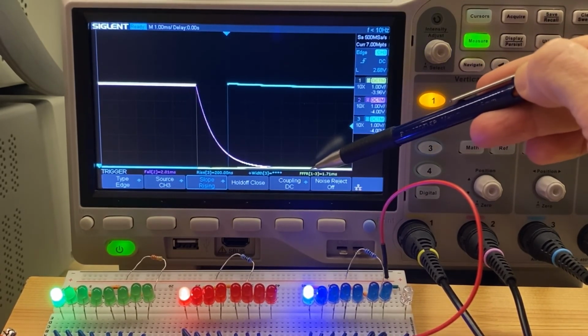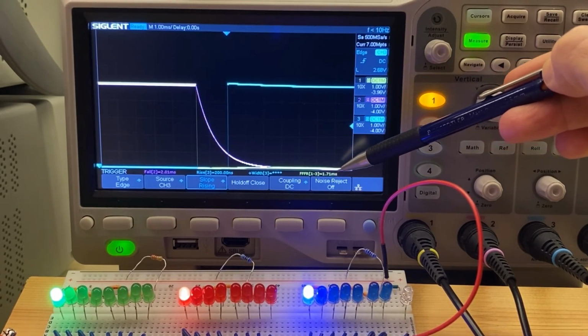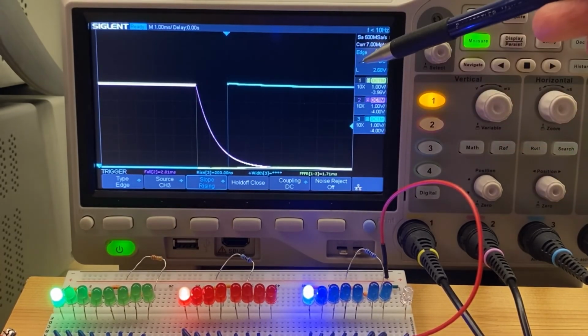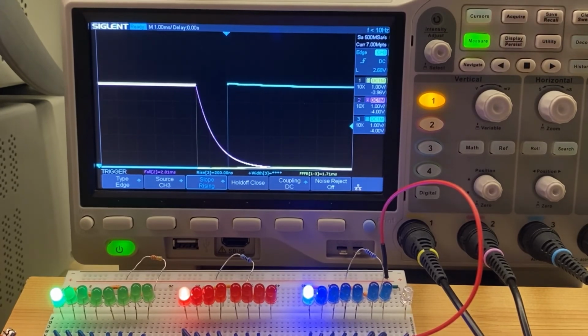So we're going to have our master reset at low for about 1.7 milliseconds, and then our clock circuit comes up and resets our circuit. Also note how the output of our clock now goes straight up to 5 volts and is no longer stuck around 3.5 as it was with the output of our BJT 555 timer. And this is thanks to our NAND gates with their CMOS outputs that are able to pull the voltage straight up to the positive rail. So it's just a little bonus that we've added to our circuit.